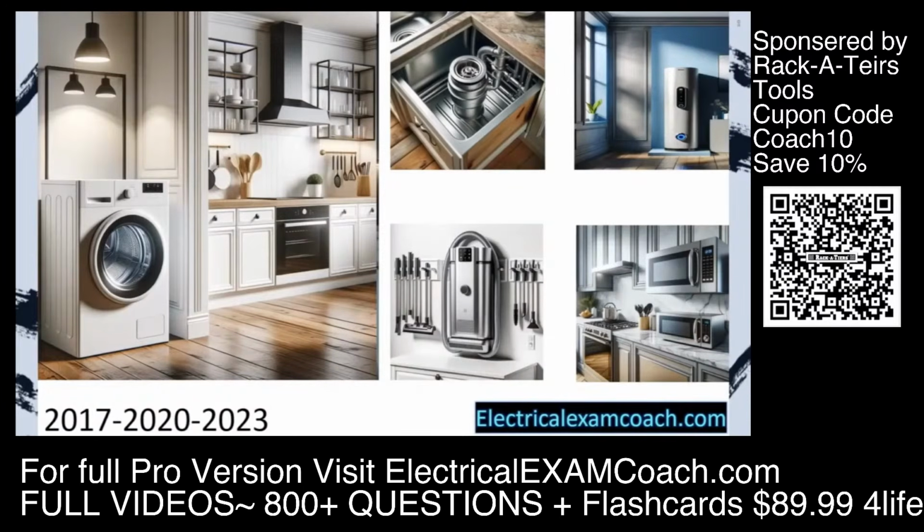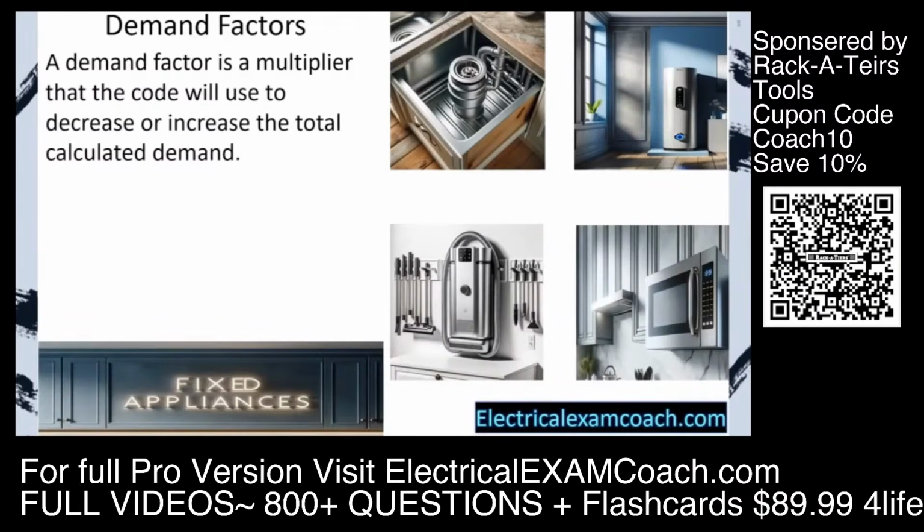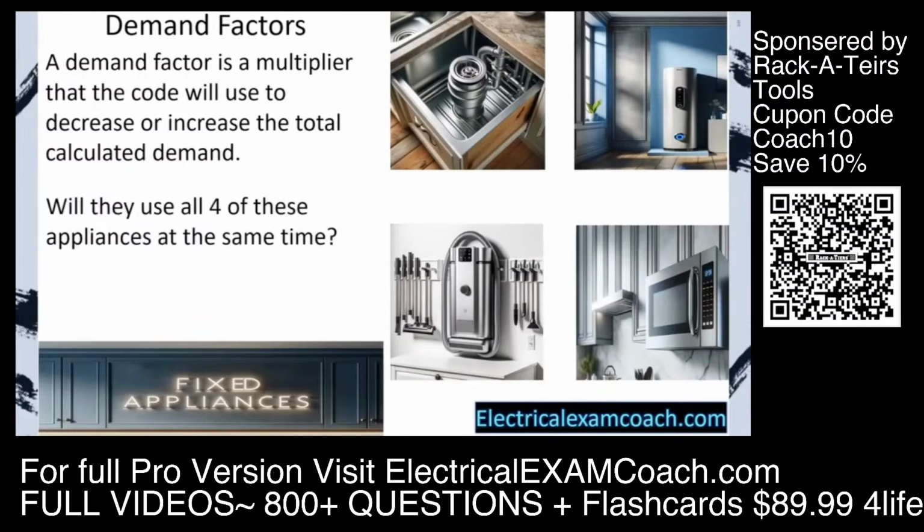Before we dive into the calculations, let's learn about demand factors. We're going to be using them for the rest of the program. A demand factor is a multiplier that the code will use to decrease or increase the total calculated demand. The question is, will they use all 4 of these appliances at the same time? And the answer is no. So the code makers have made it so we can reduce the overall demand. Instead of just counting them watt for watt, they've made some multipliers that allow us to reduce the demand that we calculate. And remember, if we have less amps, we could have a smaller service. If we have a smaller service, we could have smaller pipe, smaller wire, and a smaller overall cost of the job.